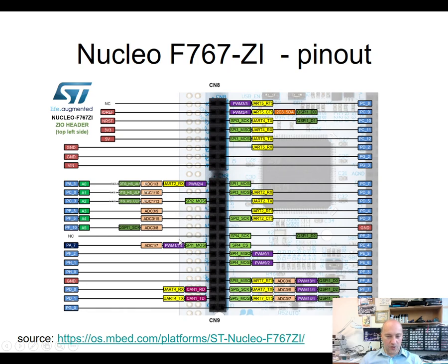And here those blocks shown in magenta, you can see that they say PWM and then some number. PWM stands for pulse width modulation, and this means that this pin can generate hardware-based PWM. So for example, we can use it to control the brightness of an LED.